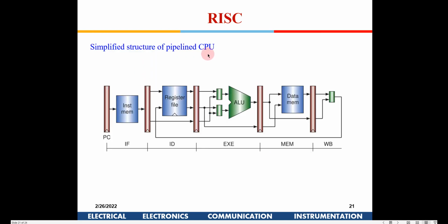Now the advantage of a RISC processor is that you can do pipelining, because they are all simple operations. You can insert a register. In the very first class we talked about pipelining, right? That kind of pipelining can be done easily here, because they are all small instructions, and between the ALU and the register file you can have a pipelining register here, and here. So the overall speed of the system will become faster.